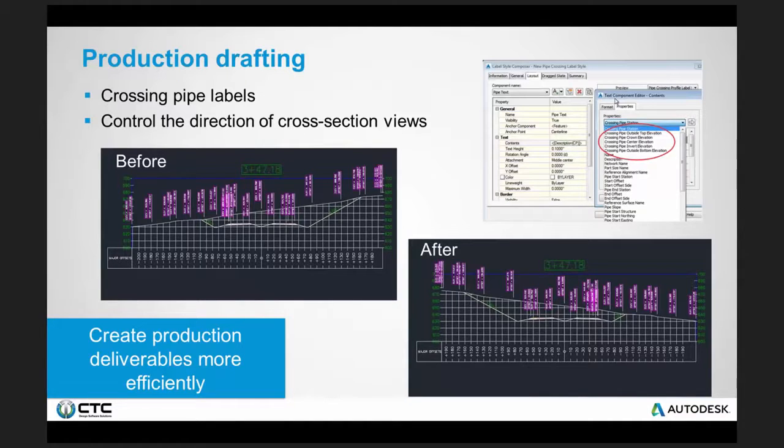So much needed improvement. And it's also there in cross sections. So we can very easily label crossing pipes with nice label objects. And there's a ton of options you'll see if you jump into your label style composer, a lot of options there for what you label, be it invert or crown or outside top or outside bottom of pipe at that crossing location. So some nice intelligence, good improvements.